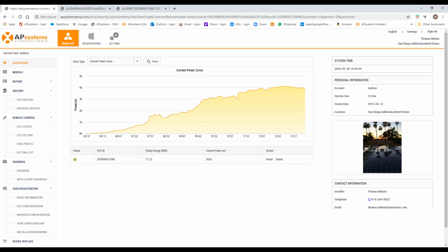Yeah, let's get the customer's name. We can definitely chat about it offline. I definitely want to help. Because if the ECU is plugged in anywhere in the house, that communication goes all the way through the house, through those breakers and up to the roof. If we can avoid that, avoid going anywhere near the arc fault breakers, that would be the key piece.